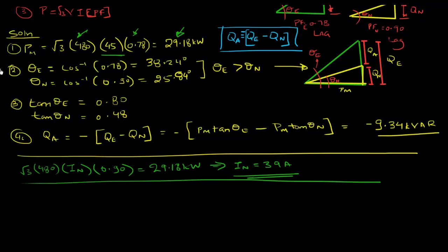Just to summarize the steps for our solution: step one, calculate real power P. Step 2, calculate power factor angle theta.